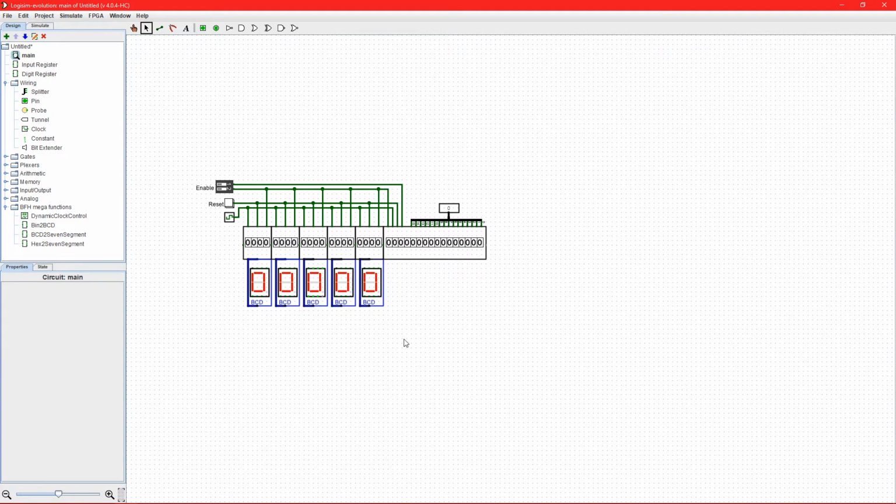I'm doing this binary to decimal conversion using hardware instead of software, and using the divide by 10 algorithm in hardware is slow. For a 16-bit number like what we have here, it will take a minimum of 80 clock cycles. That's 16 clock cycles per digit times 5 digits.